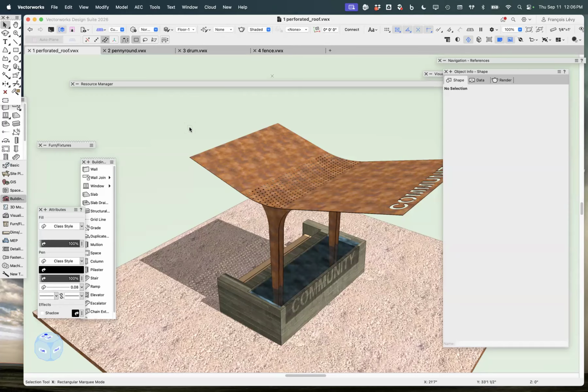If we look at the array settings, you can see that I can repeat the items along the array either by a fixed distance or by a number of repetitions. I could decide that in the X direction I wanted 20 repetitions, and in the Y direction 30, or vice versa. In this case, I've made a fixed distance of 3 inches, and then it has an offset factor of 1, which means there is no offset.